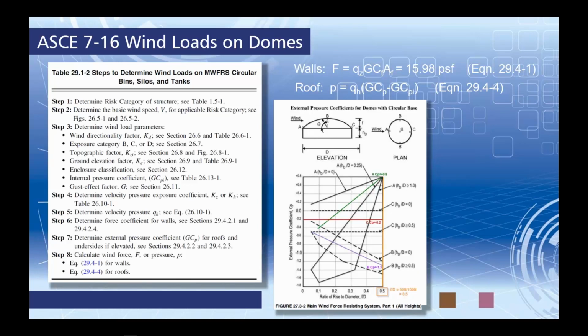So for dome roof loads, we need to first consider the wind direction, of course, and then we have some various points here where our magnitude will vary. We have points A, B, and C. Now, for the external pressure coefficients, the code allows us to interpolate, and all of these interpolations are based on the geometry of our dome.